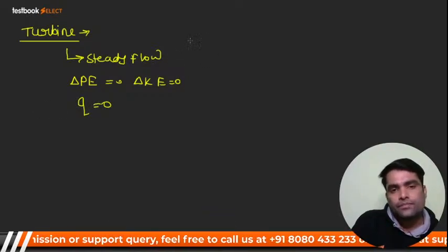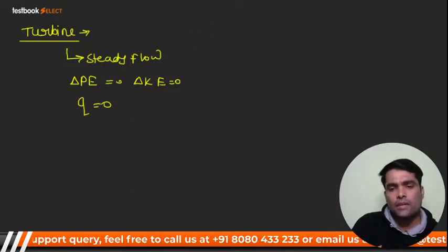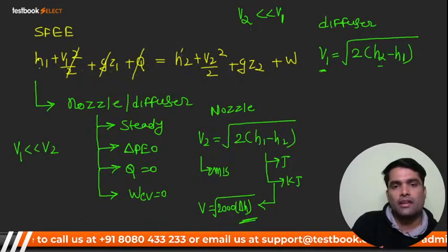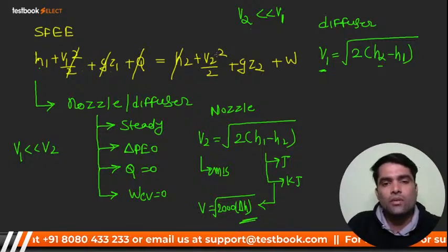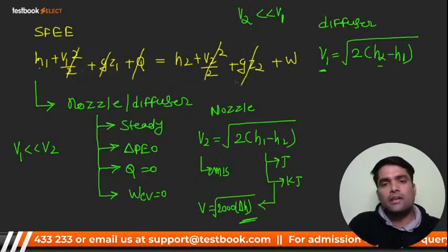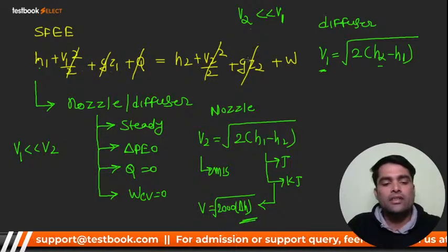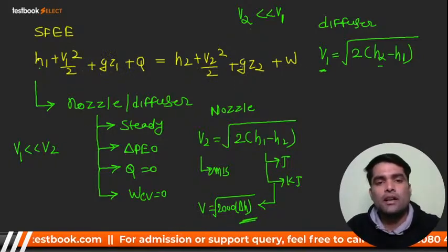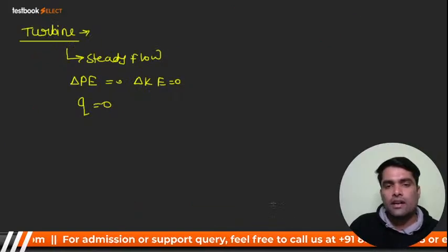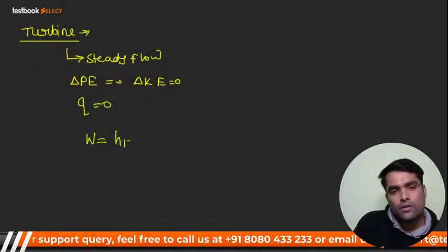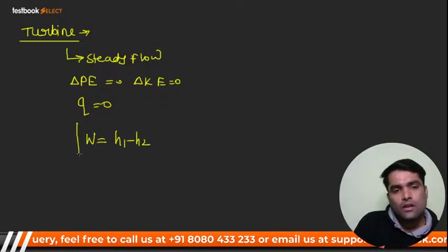And my dear, so definitely जो इक्वेशन होगी हमारी, see this will get cancel out, ये दोनों cancel out होंगे, ये भी adiabatic है, ये भी cancel out, sorry h2 cancel out नहीं होगा, this will get cancel out, this will get cancel out, we are going to get h1 minus h2. हमें क्या मिलेगा, h1 minus h2 ना बच्चा पार्टी, yes or no, right? So my dear, I can directly write, I'll get W is equal to H1 minus H2, right?